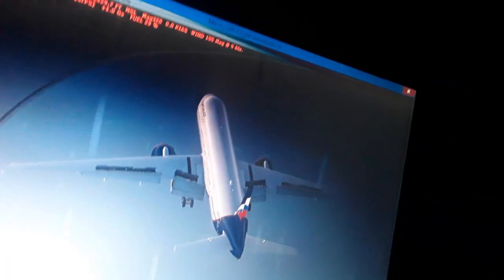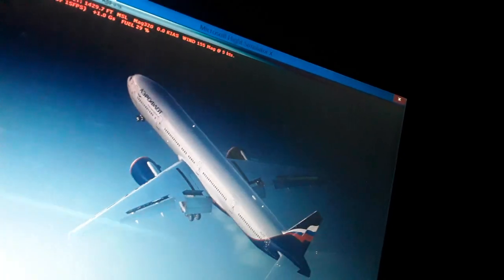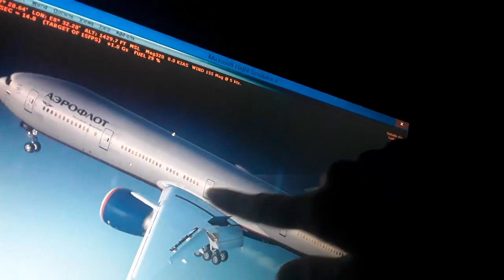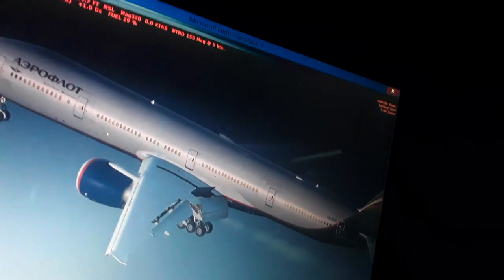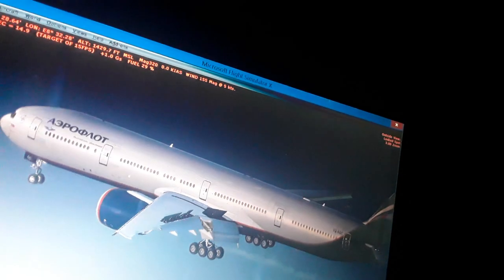You can see the wing shape. It holds the total weight of the aircraft. Also, you can see we have the mean aerodynamic chord position, here about 35% of the MAC. Mean aerodynamic chord is also the position of the maximum aerodynamic lift generated by the aerodynamic pressure of the wings. Also the position where the stall begins, where the airflow becomes detached from the wings. You can see we have the leading edge here and the trailing edge of the wings.